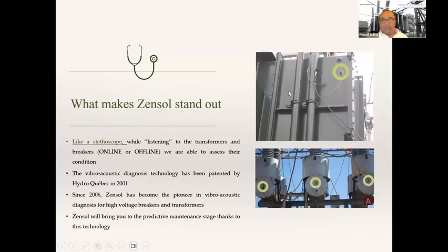Here you can see some vibroacoustic sensors, which are accelerometers, on the transformers and on the breakers. This is like a stethoscope listening to the transformers and breakers online and offline, which is the trend today, because we need not stop the breakers or the transformers.